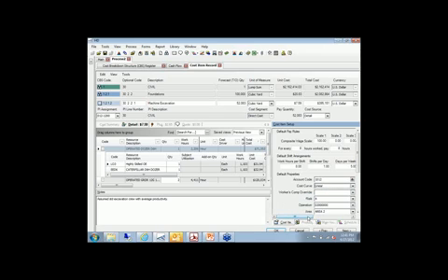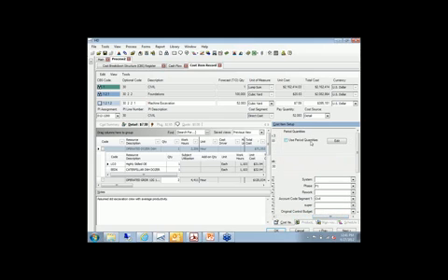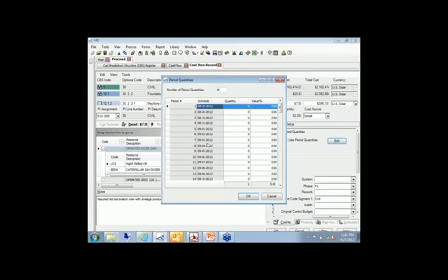Or even better, you can go into what we call period quantities. Okay, so period quantities allows you to take that 52,000 cubic yards and spread it across that period that is coming back from Primavera starting on August 28th. Okay, so we know when it's supposed to start, we know when it's supposed to finish, and we can look at this right now. We're doing it by day. We could do it by week, by month, by quarter, by year, depending on how fine a point we want to put on it. But now we could go in and spread by percentage or by quantity. So we could say, maybe 1,000 of those units are going to happen on the first day, and then the next day, it's going to be 1,200. So you can get to that level of detail, or you can do it by percentage.